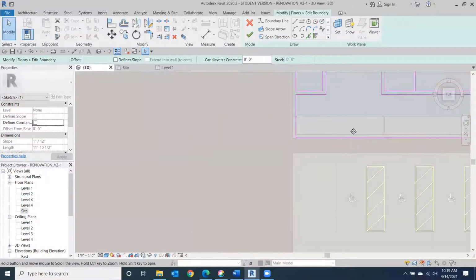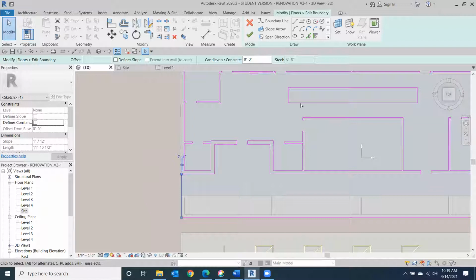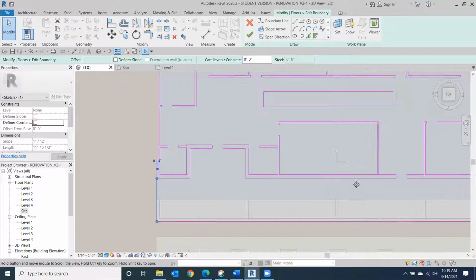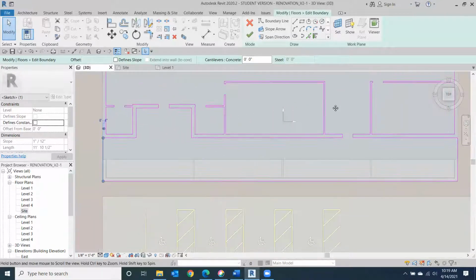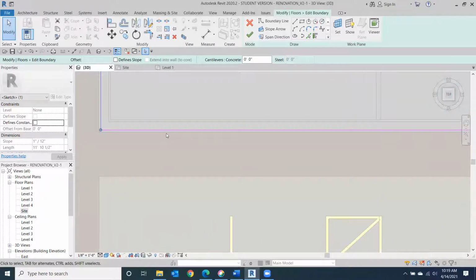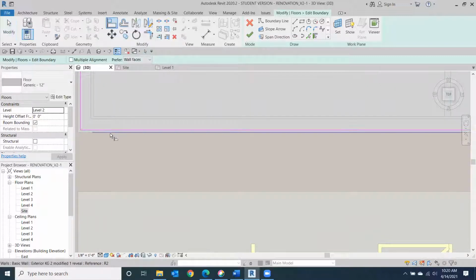I'd cover the top of that just with this section. And actually, it looks like the whole floor is one. It wasn't split into two previously. I'd go ahead and resplit this. So you have a separate exterior flooring material on the outside, and you have a separate flooring material on the inside. In order to make this flush, I can use my align tool.